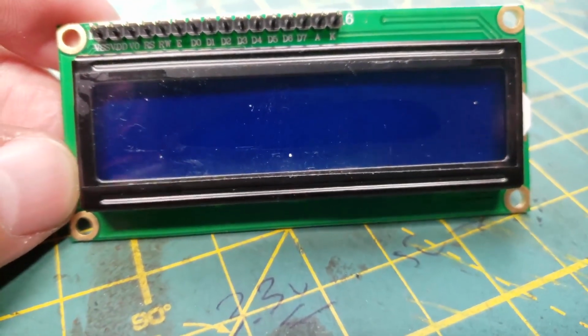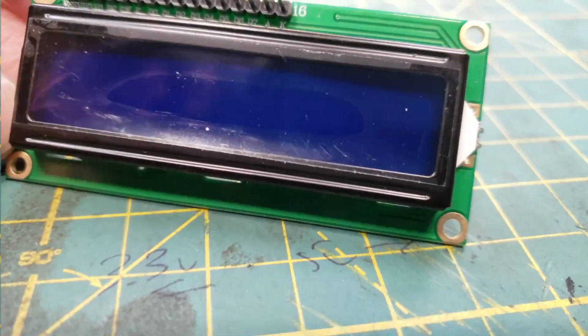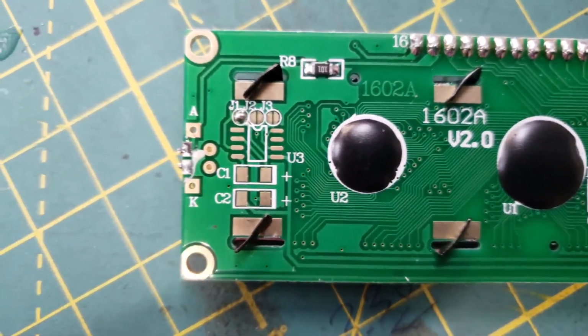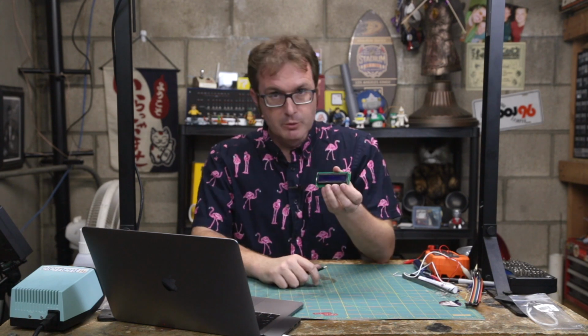So it's not just LEDs, buzzers, and motors that the Arduino can control. We can also use an Arduino to display text and even graphics. In this project, we're going to build a small fortune-telling device using the Arduino and an LCD. This is a 1602 LCD character display, which means it will display 16 characters over 2 lines. And it's just a simple alphanumeric LCD that uses a serial signal to display various text, numbers, and even ASCII pictograms. If you want to know more about these displays, go ahead and click the link up in the corner.